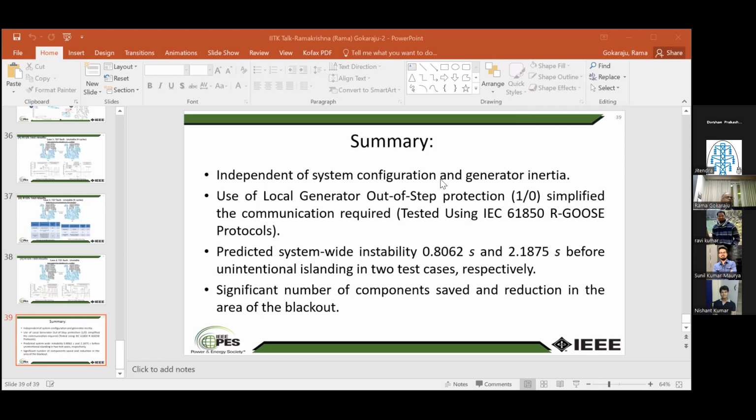Now, the controlled islanding is in terms of limiting the region of blackout. Once we do the islanding, obviously we have to do a generation-load balance. Otherwise, if the generation is surplus, we are going to have an over frequency condition. Or if the load is more, we would have to do load shedding to again restore the frequency within that region.